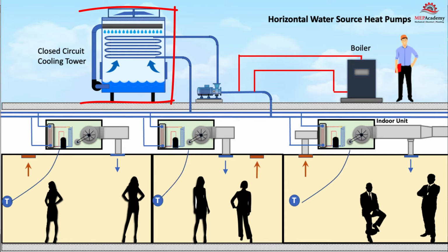The water is sent to a closed-circuit cooling tower mounted outside on the ground or roof level. The water is in a closed loop, meaning that it never gets exposed to atmospheric elements. This keeps the heat exchangers of the water-cooled heat pumps clean by preventing impurities entering from exposed water sources. With water source heat pumps, heat rejection or absorption into the heat exchanger is through water. In an air-cooled system, a fan is used for heat transfer.